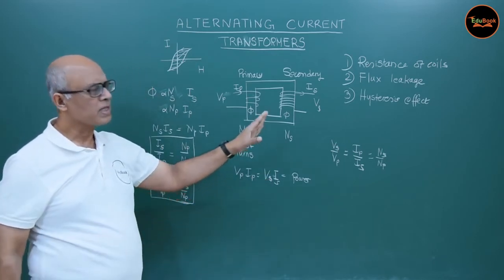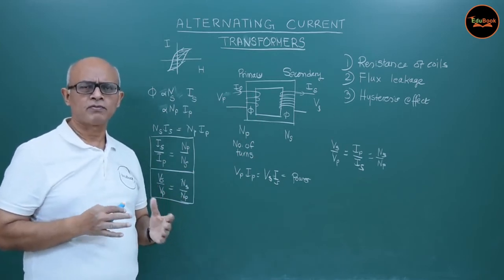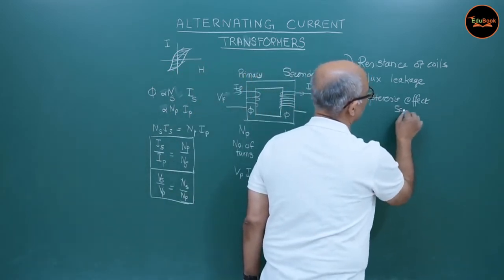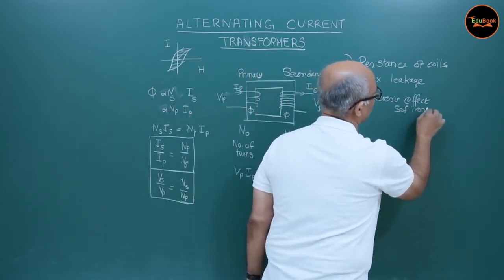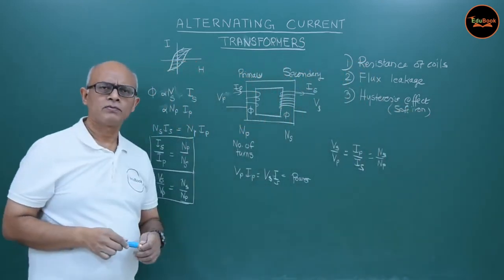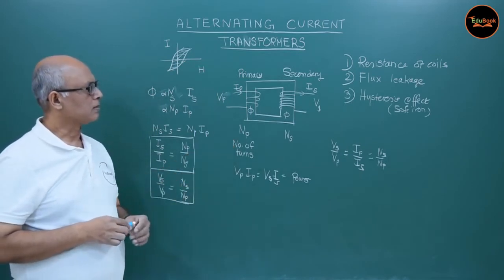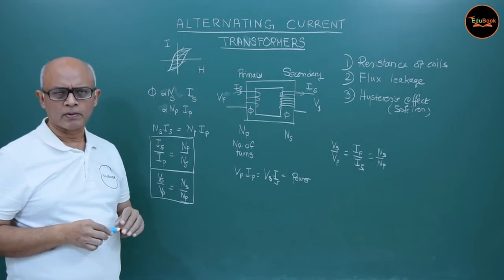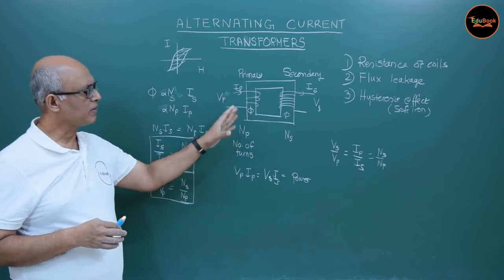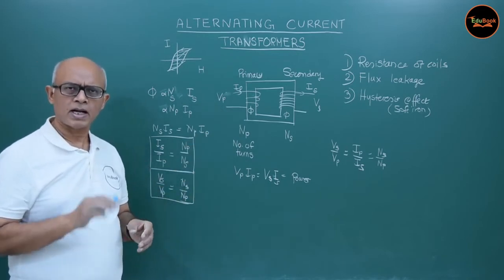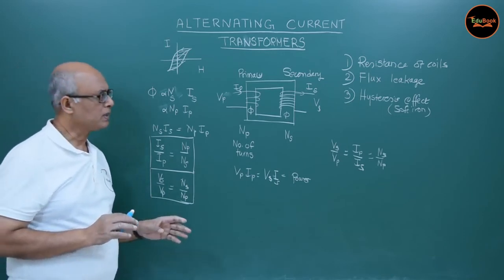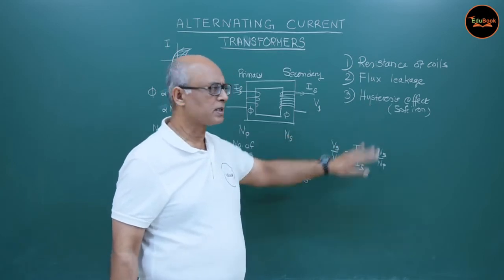The way you reduce that is by using very soft magnetic material. So, for example, you can use soft iron, which has lower coercivity and also lower retentivity. But you want high relative permeability because you want to magnify the effect of the current. So high permeability, low retentivity, and low coercivity is what will reduce this hysteresis effect.